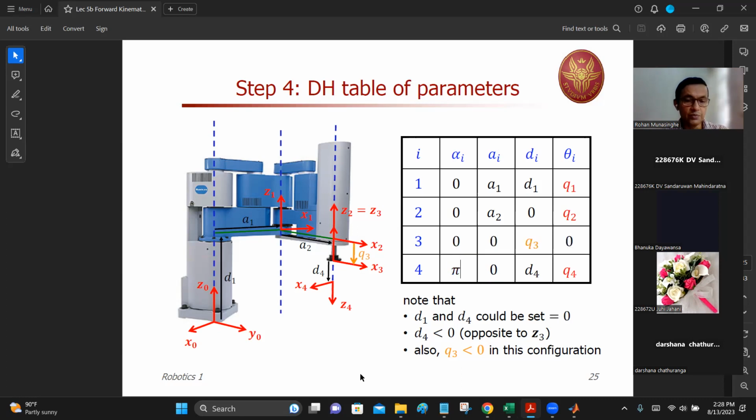Very easy. This is the process you have to apply for any manipulator, frame by frame, right? Then you can fill this DH table. It's a required skill that you know how to draw the DH table given a manipulator like this. And after that, you take, say, row by row. First row, translation, rotation.